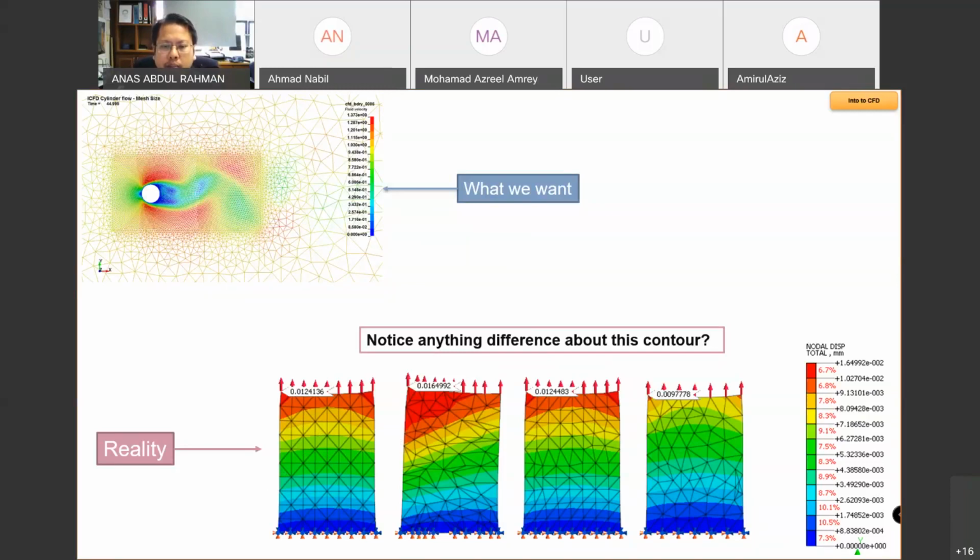We are going to learn about the combination of structured and unstructured grids. What is the best mesh generation possible? We are going to discuss that later. But by naked eye, we can see that this is the object that we have, and the mesh is nicely represented and nicely spaced throughout the object. If you see over here on the left, you can see some deformation is happening on the object because of the mesh. If you see over here, the mesh is different in sizes. Although it's not wrong, we have different sizes in terms of grid generation over here.